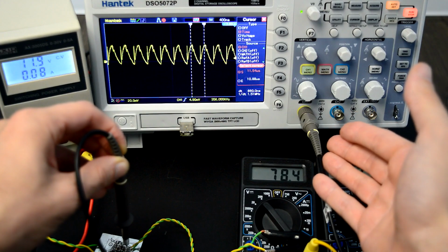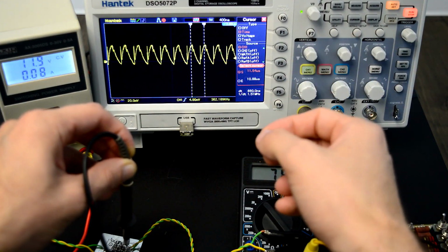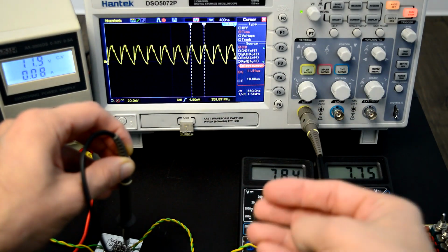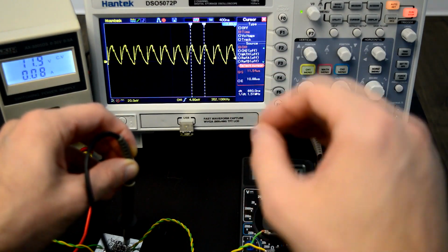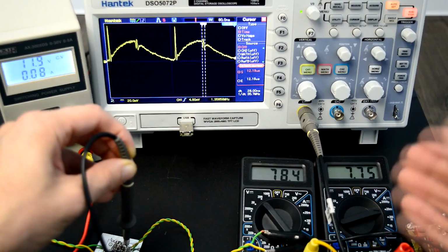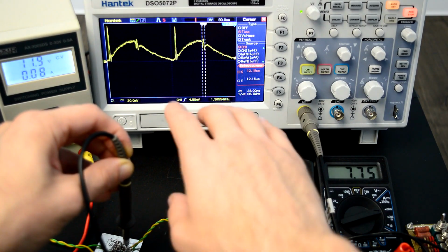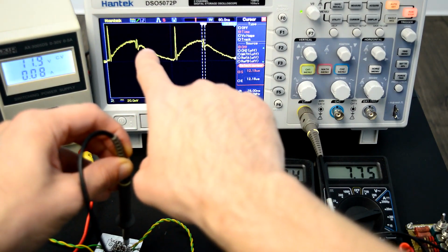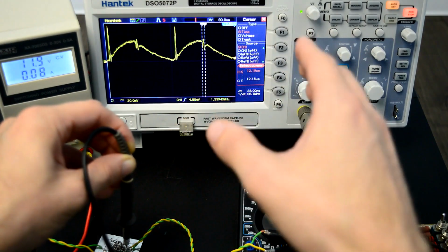And this is at a much higher frequency. Right now it's going at 1.5 megahertz, the switching frequency. This is the rate at which the power supply is switching. Now if we zoom in even more, we can see that we have even higher frequency noise. We've got this little ripple here on top, we've got this major spike here, so there's a lot going on.